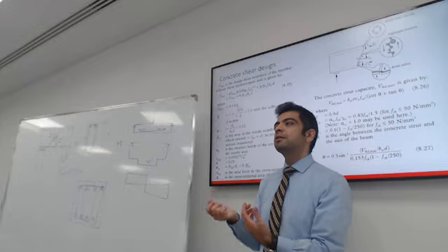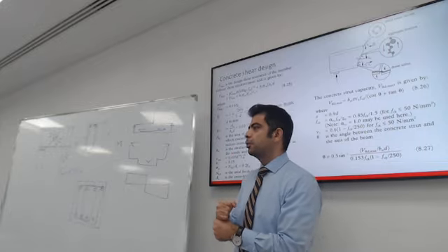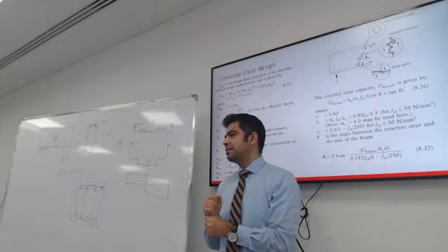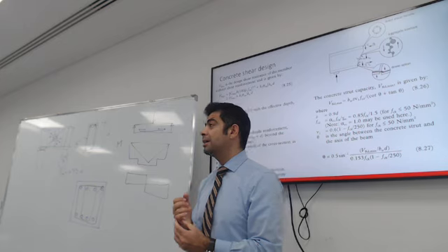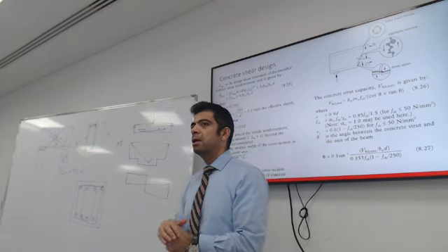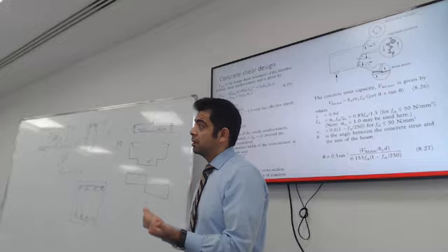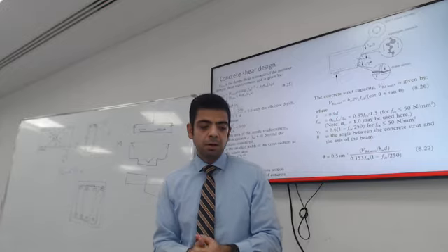So I would consider compression only from the dead load, the permanent dead load that has no chance of not being there. Otherwise, it will be more conservative to neglect the compression. Always include the tension, because the tension makes it worse. So it could fail when tension arrives.